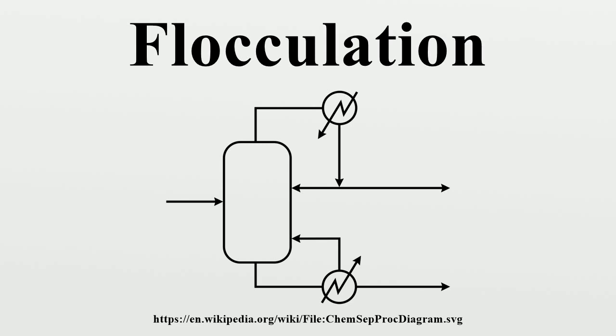Biology. Flocculation is used in biotechnology applications in conjunction with microfiltration to improve the efficiency of biological feeds. The addition of synthetic flocculants to the bioreactor can increase the average particle size, making microfiltration more efficient. When flocculants are not added, cakes form and accumulate, causing low cell viability. Positively charged flocculants work better than negatively charged ones since the cells are generally negatively charged.